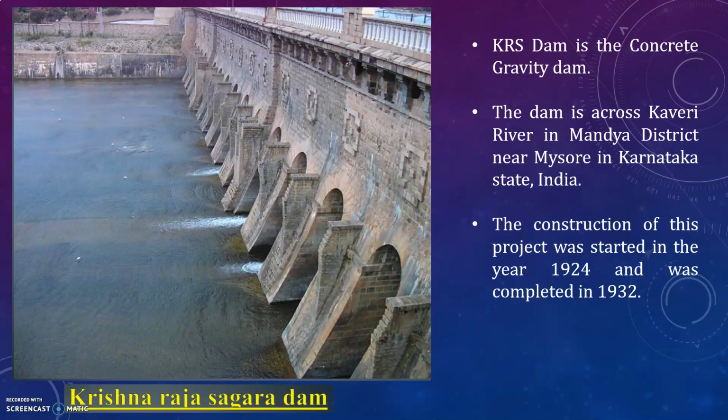There are some disadvantages also, like gravity dams can be constructed only on sound rock foundations. They are unsuitable on weak foundations or on permeable foundations on which earth dams can be constructed with suitable foundation treatment. And also, the initial cost of a gravity dam is always higher than an earth dam. Hence, where funds are limited and where suitable materials are available for the construction of an earth dam, the earth dam may be preferred.